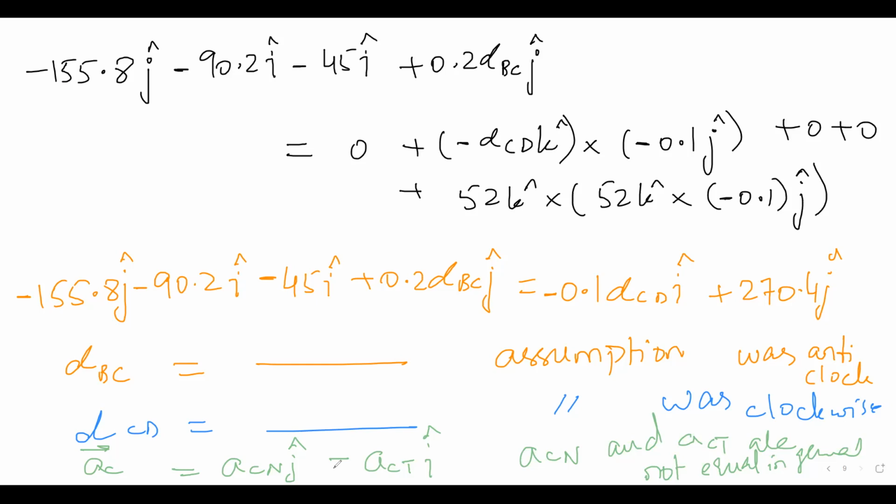Very lengthy problem. Are your answers the same? Clear? Both of you got the same answer. So now tell me the answer. What is the answer? Alpha CD is minus 1,352. So is it clockwise or anti-clockwise? Clockwise. So my assumption was clockwise. I will put a positive. Okay. What about alpha BC? 2,431. So it's 1.5. Clockwise or anti-clockwise?